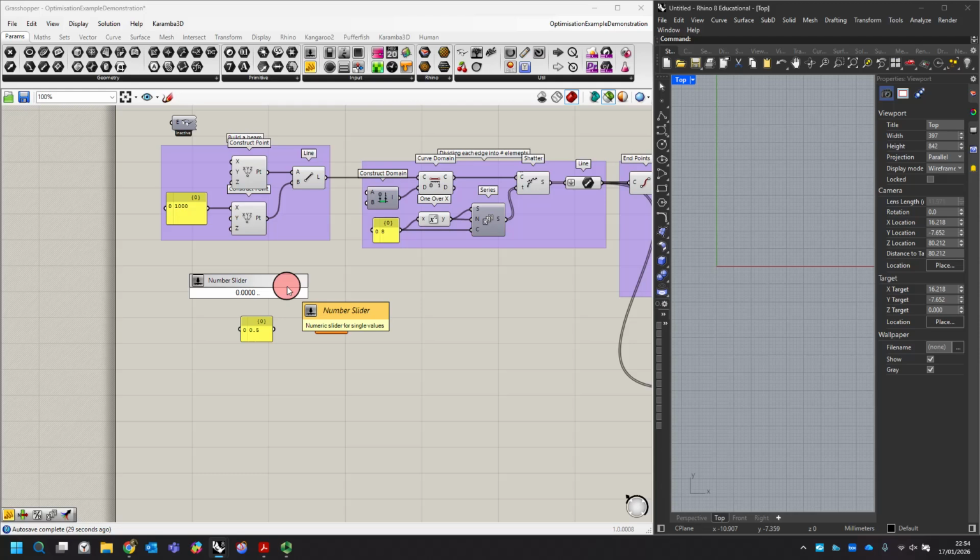And I'm going to allow it to vary all the way between being at the very end or at the start of the beam, and I want to allow it to go all the way up really very near to the midspan. We don't want it to go right to the midspan because that would cause a problem in terms of very small lengths of beam. So actually what I'll do is I'll probably just take it to 0.4900, but close enough, and then just hit enter.